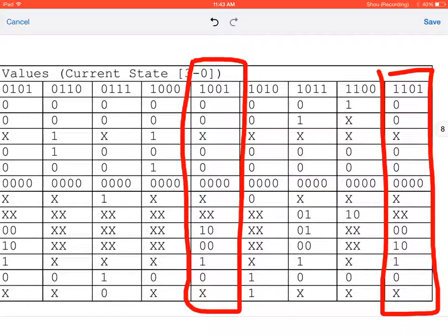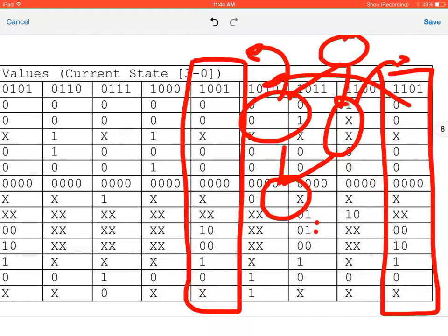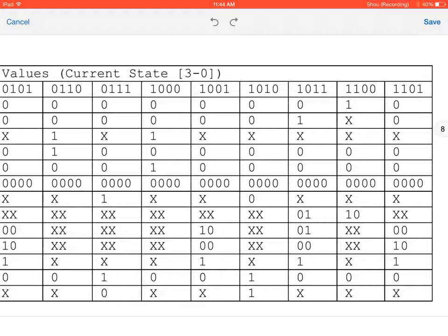So we have our instruction decode, and then it's going to branch off where we had our R-type, which is 9, and then we have our I-type, which is 13. And then they both go to 10, right? So those are both going to go to this one. So you notice how these are the same, except, right? That's where it changes. So that's the difference between R-type and I-type.